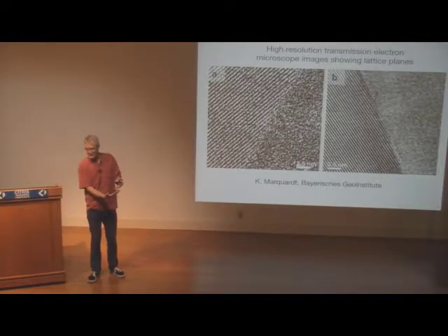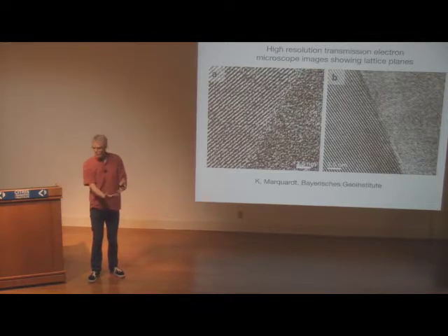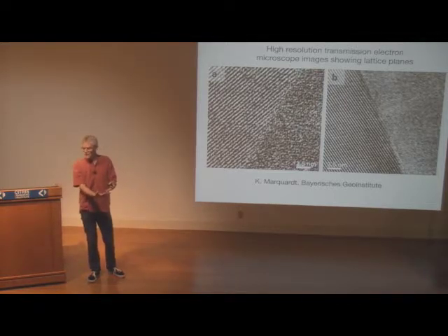Yeah, this is an ongoing debate, right? It's not very easy to get these images. Essentially, you have two crystal lattices, and you have a TEM foil that's thinned enough so the electrons can go through the thinned material. And then if you tilt the grain boundary, you can get an apparent overlap of the lattices on either side, because your transmitted electron beam goes through both lattices, and it looks like they overlap.